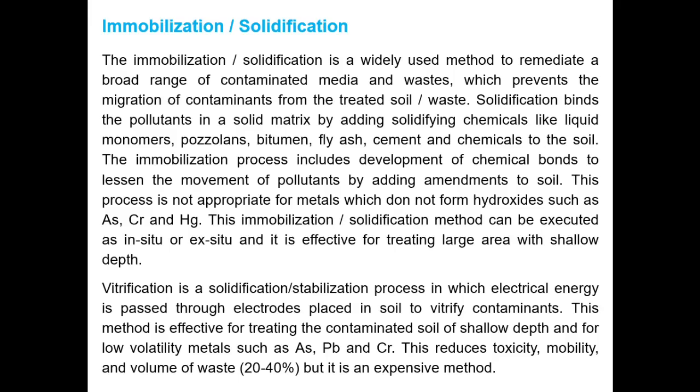Vitrification is a solidification or stabilization process in which electrical energy is passed through electrodes placed in soil to vitrify contaminants. This method is effective for treating the contaminated soil of shallow depth and for low volatility metals such as arsenic, lead, and chromium. This reduces toxicity, mobility, and volume of waste, that is 20 to 40%, but it is an expensive method.